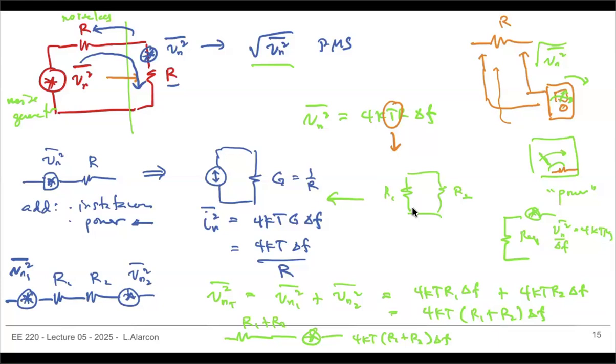We will have a bunch of other examples, but let's just try and start with understanding very simple resistor thermal noise. We know that it has power, and we can characterize it with mean equal to 0 and variance equal to 4kTRΔF, and it also is white. Again, very important, its spectral response is white, because there are other noise sources that do not have a white spectrum. So any questions here?